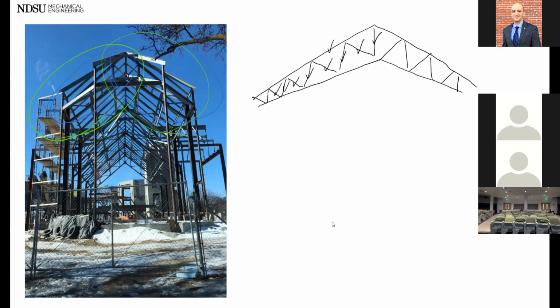We're going to break down this structure and you're going to learn how to analyze the forces. Usually as an engineer, what you are asked is to design a structure like this. They give you the loading on a roof, which is going to be a distributed loading, and based on the loading you have to design and find the forces in the members. For this class, what we usually do is give you a structure and ask you to find the loading in each member. Okay.